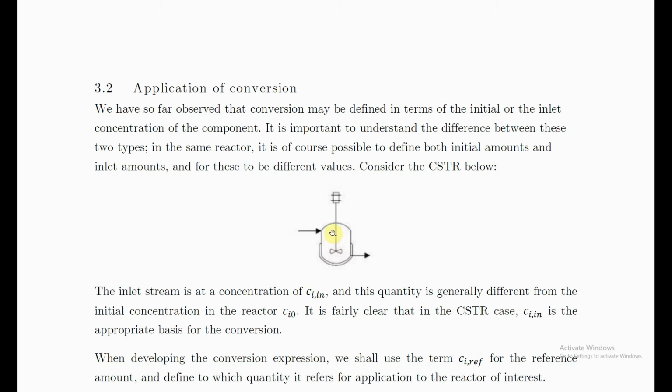And if the level goes up, and maybe if there's more reactant, if you've added a lot of reactant that caused the level to go up, then that means the concentration of your other species become effectively diluted to some extent. Or if the level goes down, then it's more concentrated. So that is going to change the concentration in the reactor, and that's going to complicate our efforts to identify a reaction rate and so on.